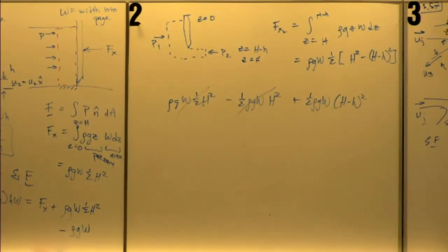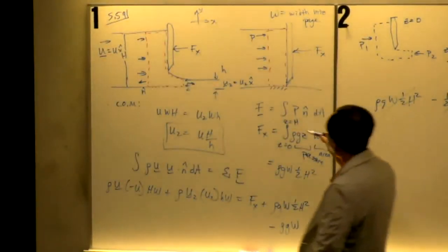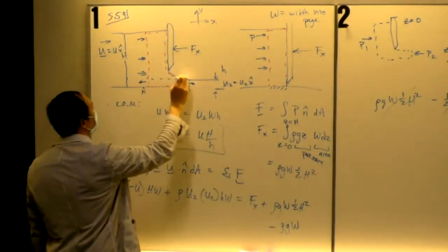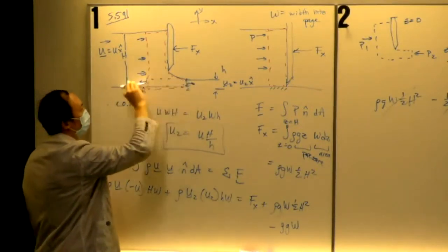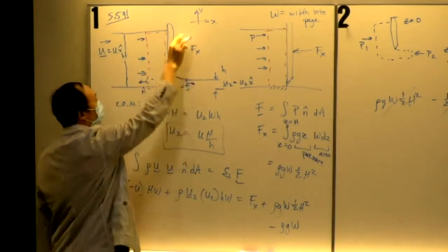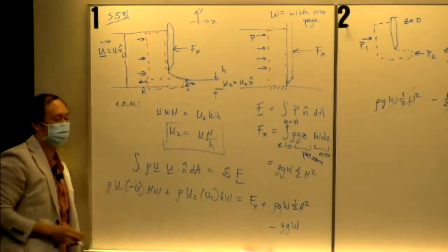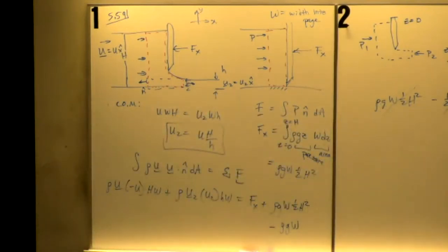I guess physically, if you really wanted to avoid all that math, you could have just looked at the board and said, when I have this flowing, these two parts are going to cancel. These two parts are equal and opposite because remember Pascal's law says pressures are equal along horizontal lines. So I can just ignore those, and only on the left is that. And I can just integrate between little h minus h and 0.